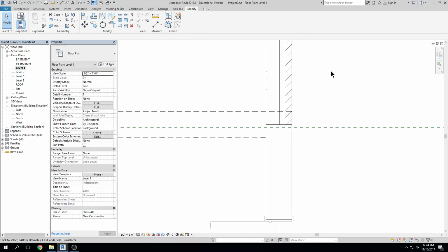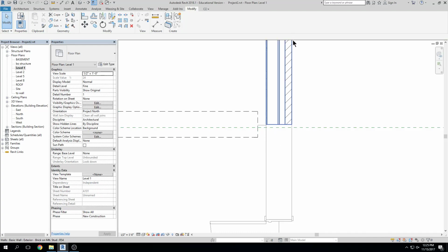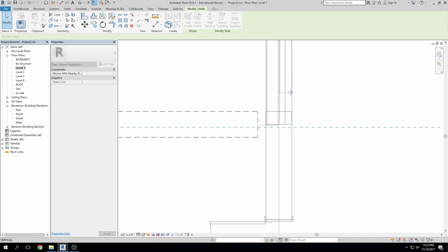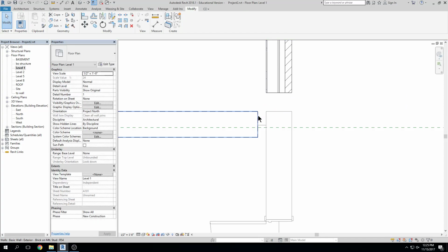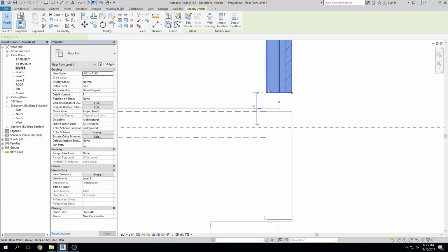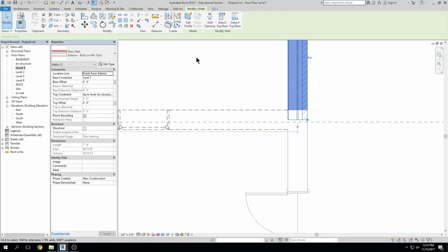Yep, exactly. So I click on wall join again, click, click, escape. I drag this guy in, even a little bit more than I need to, and I then pull this guy up. I'm essentially unjoining them. I'm defining where I want all of these elements to live, and then bringing them back together how I want to see it happen. Oh, this one's being difficult.